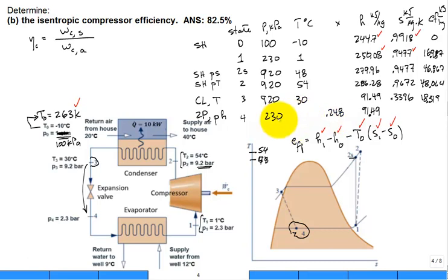And the temperature will be the saturation temperature of negative 6.55. If you want, you can calculate the entropy, which is 0.3531, and the flow exergy of 14.767. That takes us a while, but if you compute the table in one place, it helps organize the information, and it's a lot better.